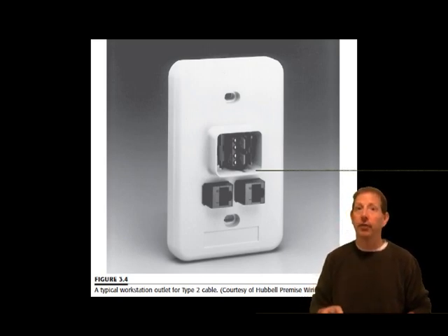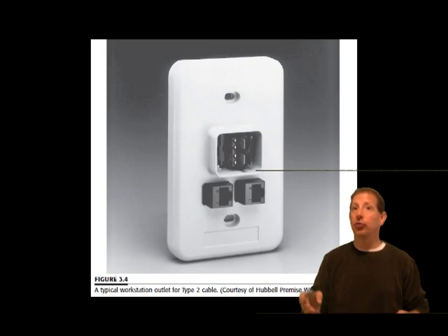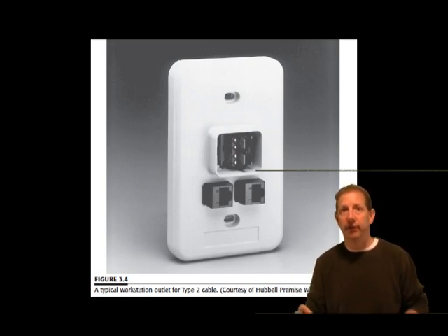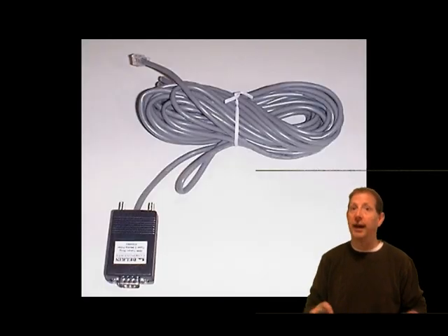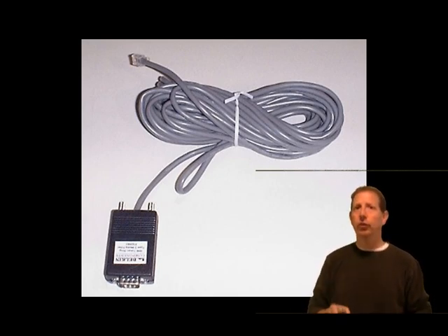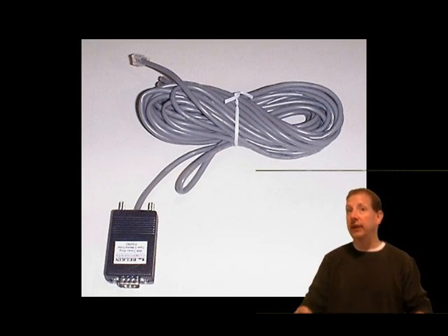When Type 3 wire is used as station cable, a special adapter cable called a media filter must be used to match the 105 ohm cable to a 150 ohm device interface, such as token ring interfaces. Some newer token ring interfaces also have a 105 ohm modular jack, which eliminates the need for the media filter. Similar media filters may be used with 100 ohm Cat 3, 4, and 5 cable.